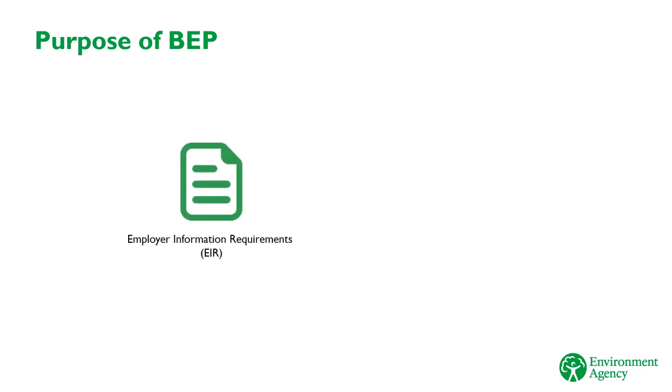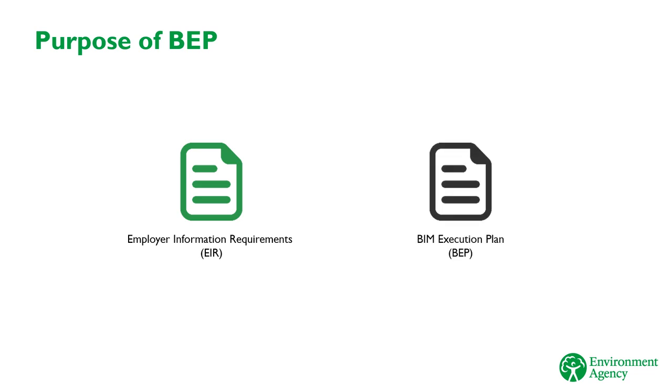In Module 2, we saw that the Employer's Information Requirements sets out the EA's minimal technical requirements for managing data and information in projects. That document sets out roles and responsibilities for the EA and the supplier, and explains technical requirements around modelling, information transfer, file formats, and so on. The supplier's BIM Execution Plan is a response to the EIR, so it explains how the supplier will meet the requirements we've set out as the client. The two documents work together to define how BIM will be implemented in a project.